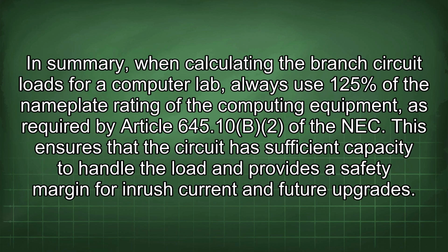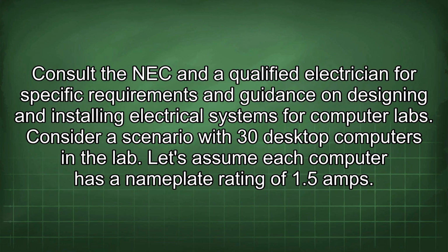In summary, when calculating the branch circuit loads for a computer lab, always use 125% of the nameplate rating of the computing equipment, as required by Article 645.10(B)(2) of the NEC. This ensures that the circuit has sufficient capacity to handle the load and provides a safety margin for inrush current and future upgrades. Consult the NEC and a qualified electrician for specific requirements and guidance on designing and installing electrical